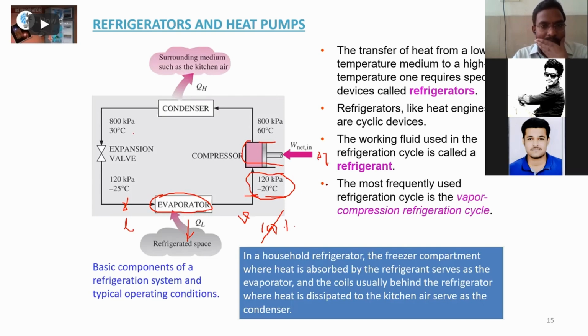Actually, in the video, somewhere I heard that in the compressor, because of the increase in pressure, the temperature also increases, right? And he mentioned that that is unavoidable, but actually that is a required one. Why is this increase in temperature required? Now see, when working fluid enters the evaporator, it is expected to have a temperature lower than the food. Then only it is going to accept the heat from the food, right? And that we can achieve through the condensation and expansion valve, because some temperature drop will be over here and further temperature drop will be over here after the expansion valve, so that we can reduce the temperature of the working fluid lower than the temperature of the food.